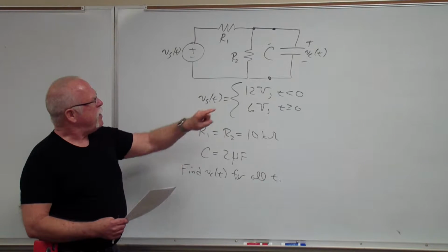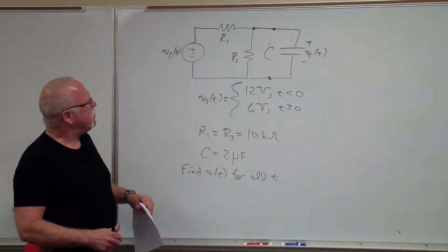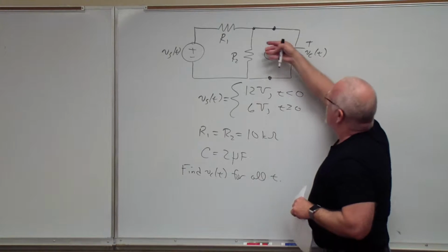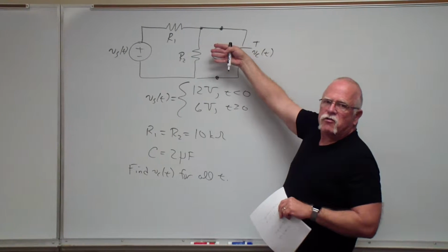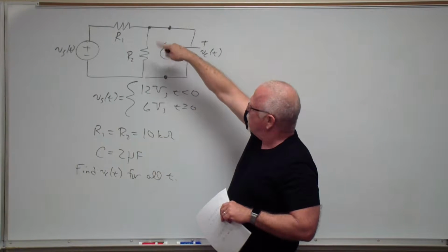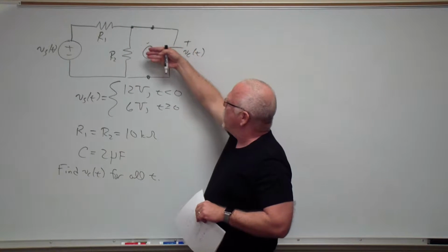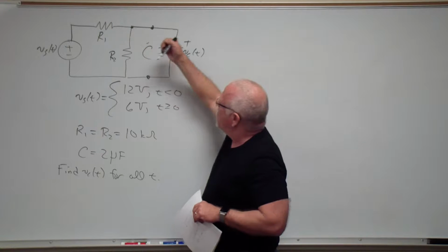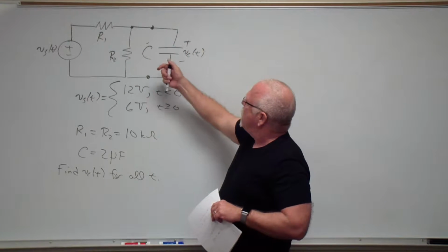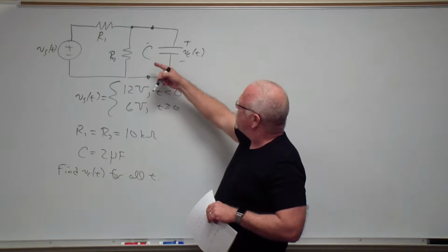And we're going to first find the initial conditions by solving for t less than 0. There's a little bit of insight you can have here, looking back from the capacitor terminals. If you thought of that as a Thevenin equivalent, you would just see a voltage source of half the strength because of the voltage divider between R1 and R2 being equal. And looking back, the Thevenin resistance would be R1 parallel R2. So our time constant ought to be R1 parallel R2 times C, and we can anticipate that. But let's go ahead and derive it. We'll find the initial condition first.